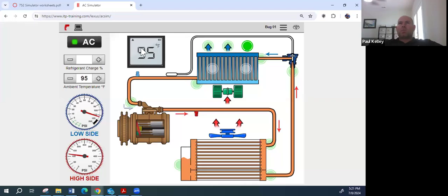And do you see what the temperature reads? When I picked up the thermometer, it showed me the temperature. I could put on multiple points. But if you look, the first thing we do is just measure the air coming out of the vents. What would we call this? Is it blowing warm, cool, hot, cold?